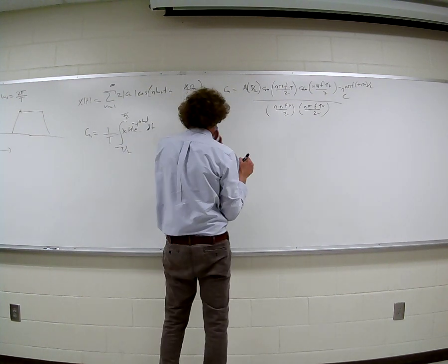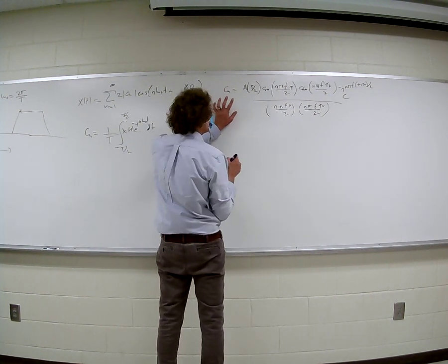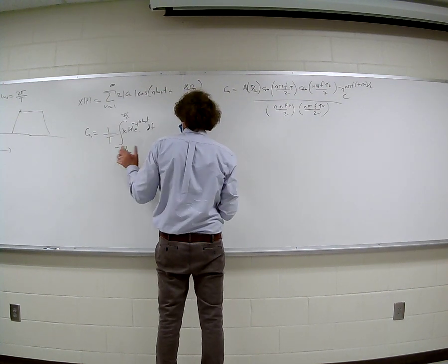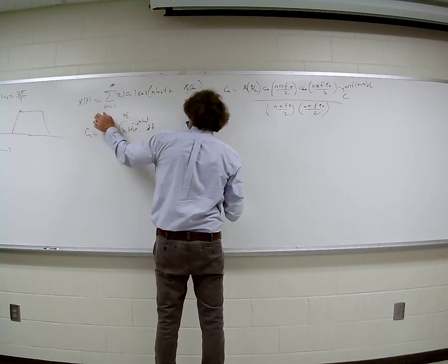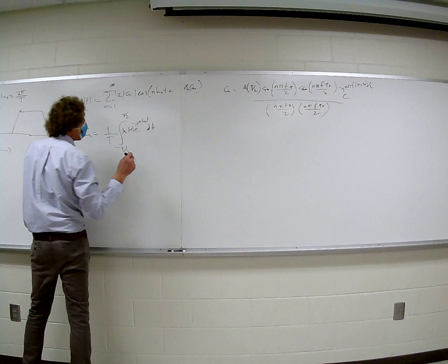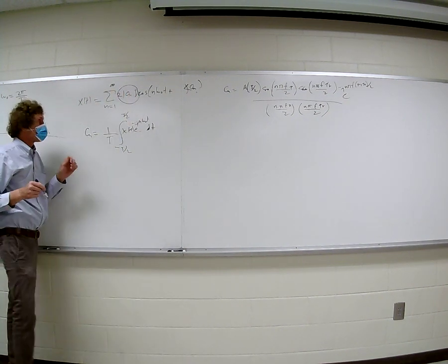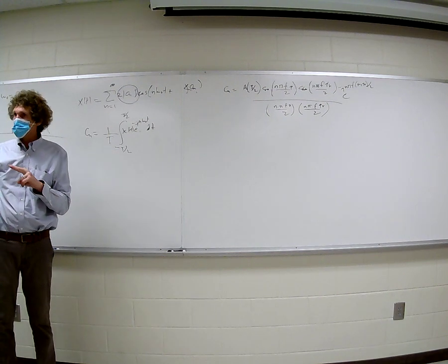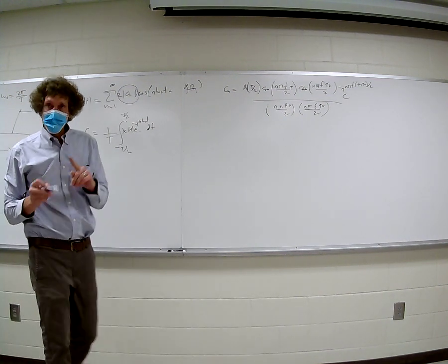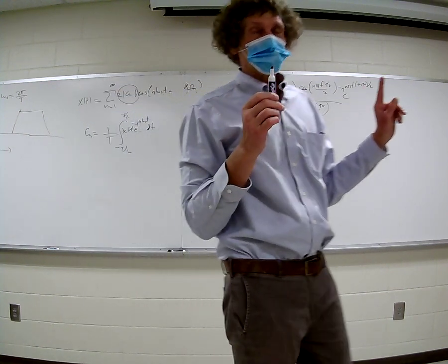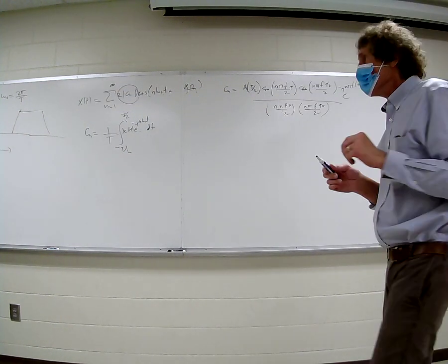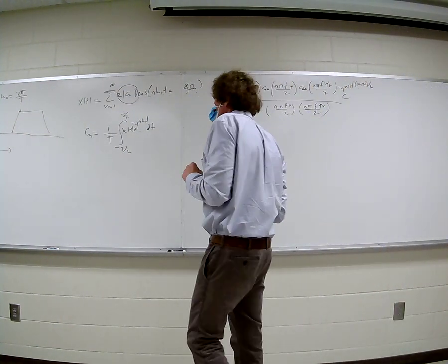So when we look at this series and we're talking about the Fourier components, you see how there's a factor of 2 c of n magnitude there, right? This is so important, what I'm about to show you. Y'all with me on this? Now that means versus frequency, if you wanted to see the strength of that signal, this c of n is in volts; if you square it, it would be the power.